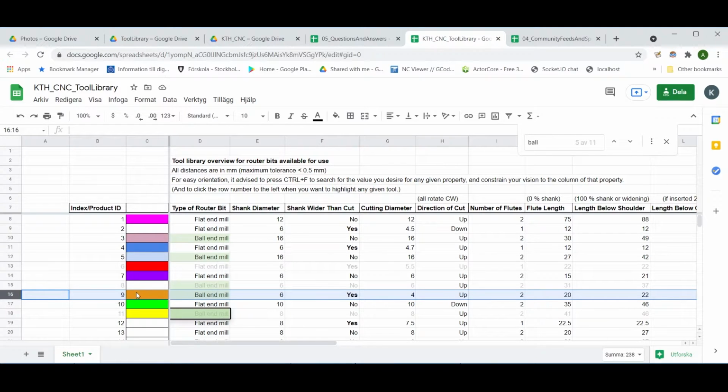And this was the one that Alistair used. But 4mm in relation to the roughing of a 10mm tool might be a far too large gap. If the gap between the roughing toolpath tool diameter and the finishing toolpath tool diameter is too wide, then the substantially smaller tool will reach into cavities which could not have been cleared by the roughing toolpath.